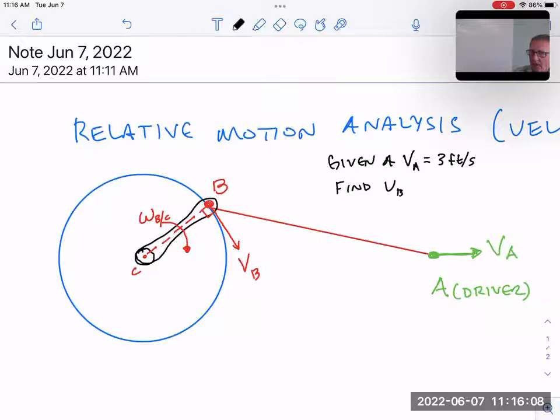So how does the velocity of one thing connect to something else? Relative motion analysis. I know the green velocity, and so relative to that, what's the red velocity? And ultimately both velocities. What's the angular velocity and the linear velocity at that point? How does the explosion in the piston affect this crank arm? Therefore, how fast is my car going to go down the road?